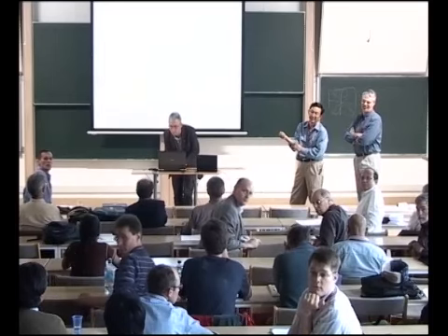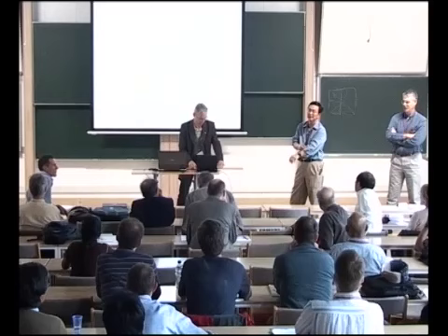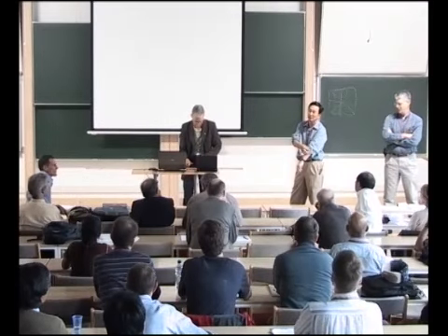We have one, two quick questions. Yeah, a short one. When you do the blowing and suction and the drag is below laminar drag, doesn't the velocity profile have an inflection point? So wouldn't that make it unstable, prone to more separation and things like that?